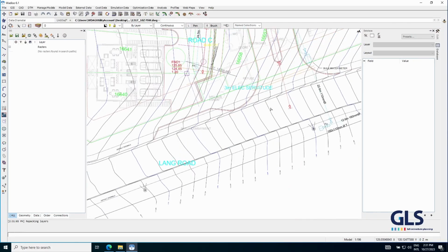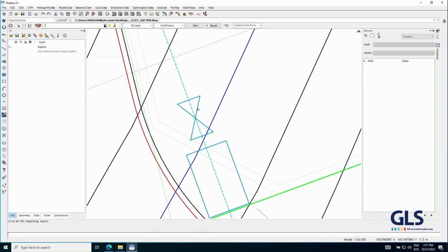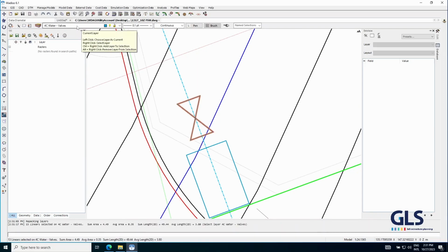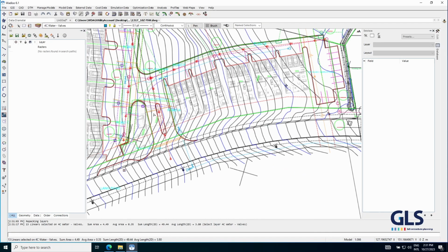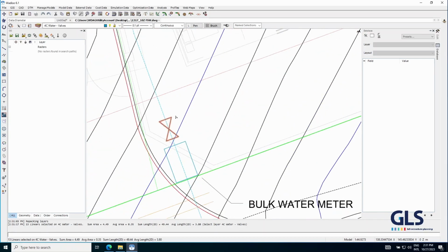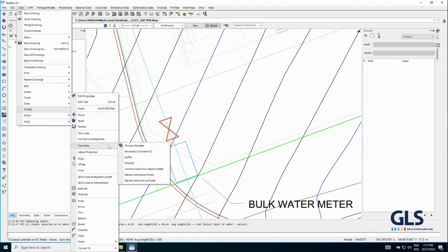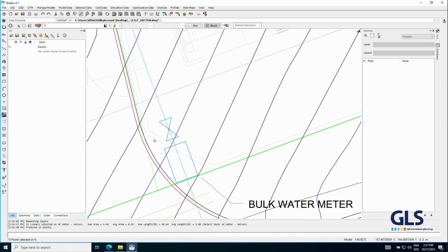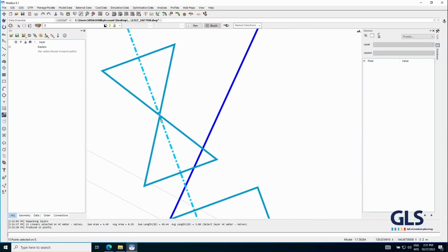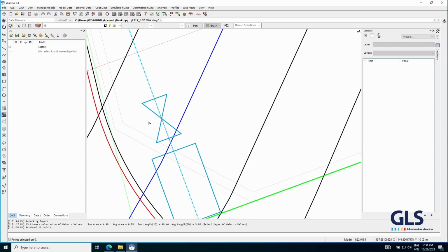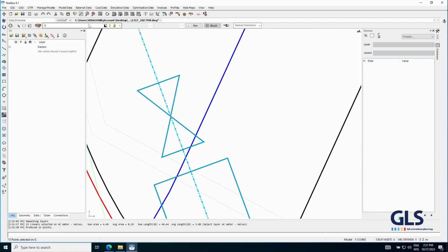So for instance, if we look at this drawing, we have all these valves, they are polygons, so I can select the entire layer. So all of those valves can be selected, and then I can say CAD, modify the geometry, and I want to extract the centroids as points. It'll actually extract that centroid, remembering that these CAD operations always add new entities to the current layer, so it's always a good idea to add a new layer that you actually want to have control over.